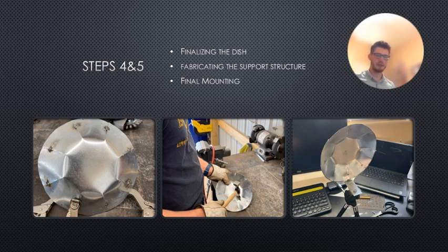As you can see here, in order to achieve that, I used these welding vice grip clamps to clamp each petal together where I had already bent them and overlapped them. And then I welded them using a MIG welder. I'll talk a little bit about the challenges in the construction process later.